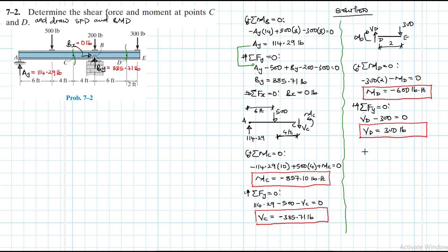Alright. So remember issues of negative and positive. When a beam bends like this, our convention is the beam is positive, and when it bends like this, we say the bending moment here is negative. Think of bending where it's able to hold water: the beam, when it bends like this, is experiencing a positive bending moment. When it spills off water, it has a negative moment.